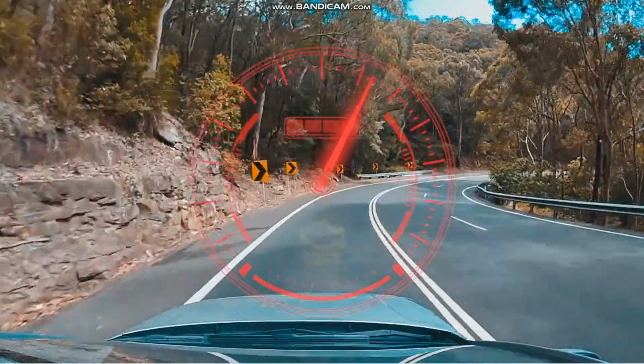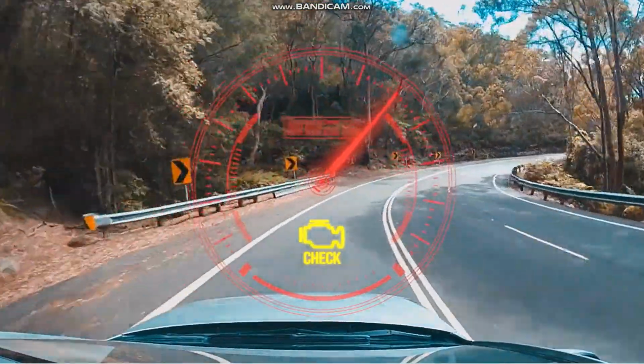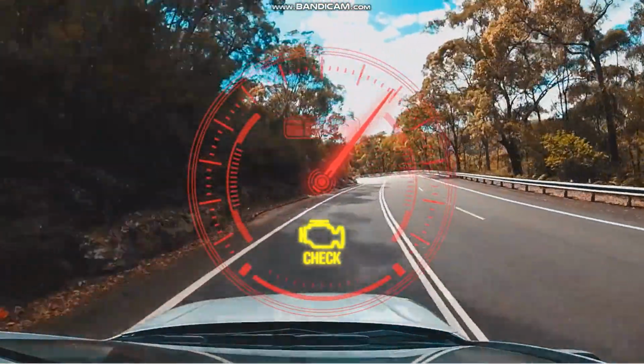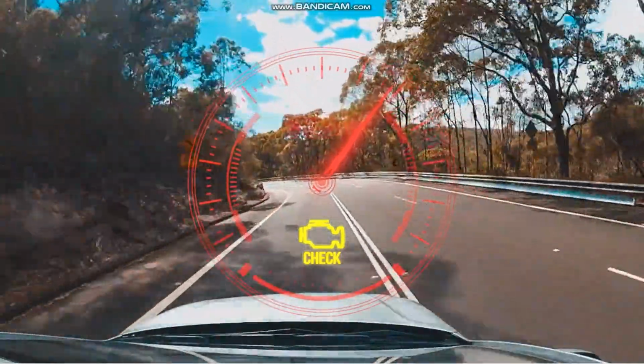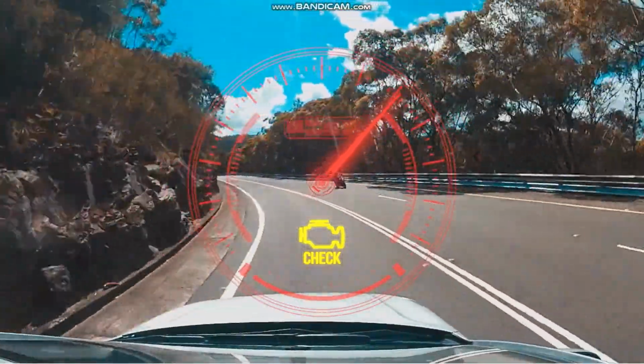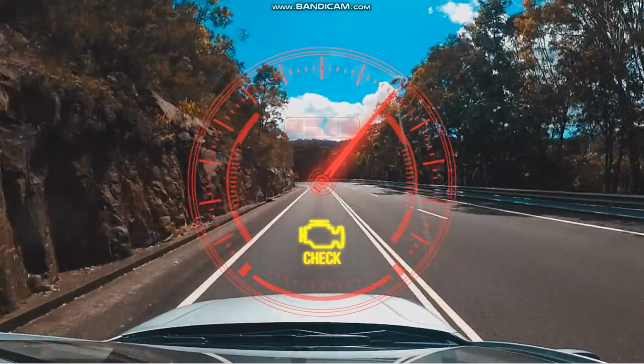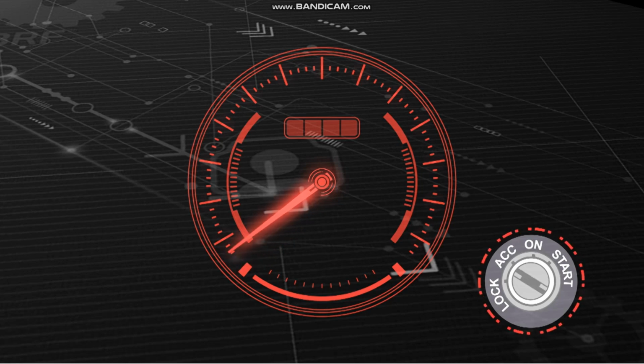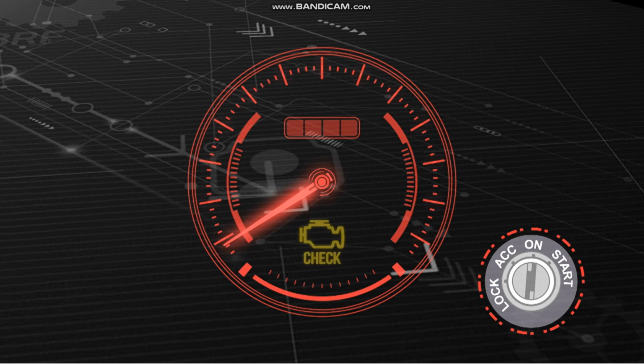The only obvious difference from a driver's perspective when operating a vehicle manufactured to OBD2 standards is the presence of an orange warning light, referred to as a malfunction indicator lamp or MIL. The OBD2 standards determine when this lamp must illuminate and how it illuminates. With the ignition switch turned on, the MIL will illuminate for a short period, which is effectively a bulb check to confirm it is operational.